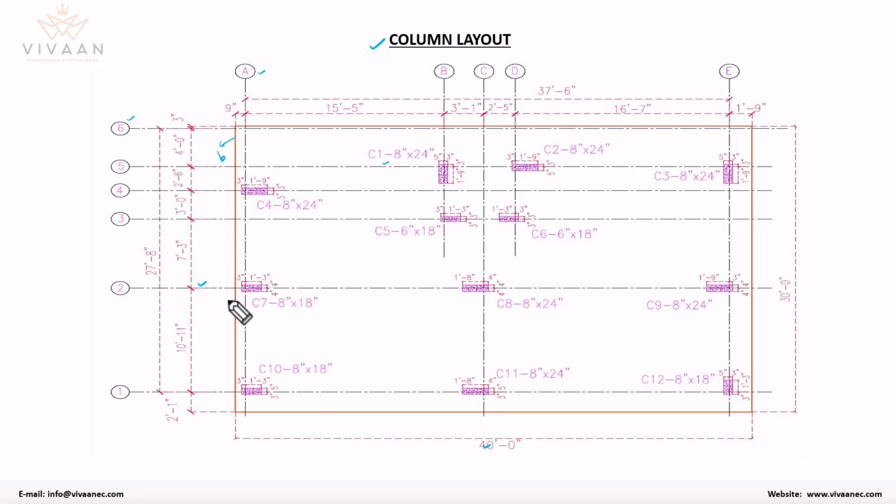Because of the combinations of loads, even when you are in a zone 2 area of earthquake, although the earthquake is less on that side, the Indian Standard Code gives us the loads which are apt for that zone 2. Zone 2 will have lower earthquake loads, zone 3 a little bit more, zone 4 more, and zone 5 the highest. So the earthquake zones have to be considered irrespective of the place you construct the building, and for a multi-storied building we mandatorily need to consider these loads while we design.